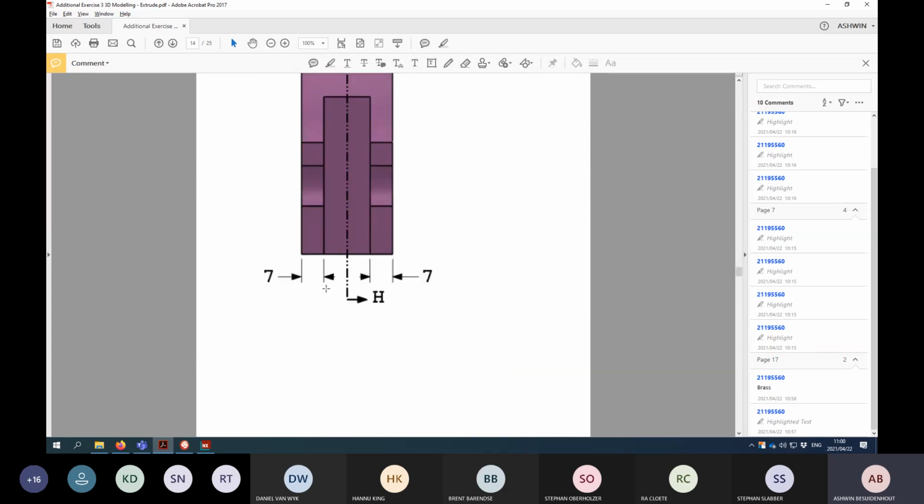With this one, I'm gonna draw on the top view and extrude upwards. That would be the easiest. Instead of drawing on the front view, you can draw in the front view and extrude in as well, but then you'll have to make sure that the height of the thing that you're going to cut out is sufficient. So I don't want to worry about whether this height is high enough and so on. I'm just going to draw it on the top view.